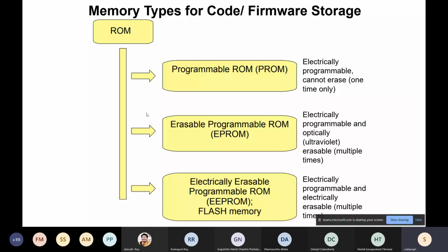Now, coming to the advantage and disadvantage, flash memories are typically erased in segments or in pages. Segments and pages mean you cannot delete one memory location, one byte, from a flash memory. If you want to store, let's say, some 10 or 15 bytes of data, you don't want to delete 1024 bytes of data and then update all 1024, when only 10 are new data out of that. That is very inconvenient for flash, and it also affects the endurance of flash because you are losing one write delete cycle.